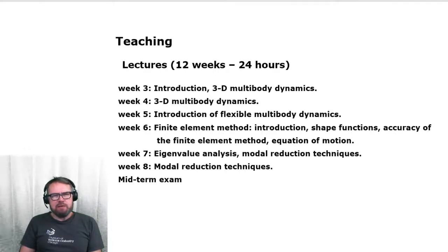And there's one lecture that is dedicated to the theory of the finite element method. So I will get started from very fundamentals. We're going to discuss shape functions, which are like the soul of a finite element. We're going to look a little bit at the polynomial expansion that is needed to build the shape functions, and how the selection of polynomial expansion will affect the accuracy of the finite element method. And a little bit about how you can do dynamics with the help of the finite element method.